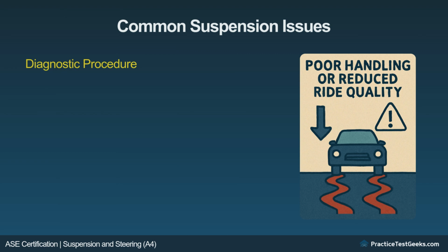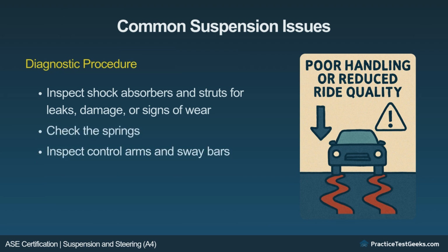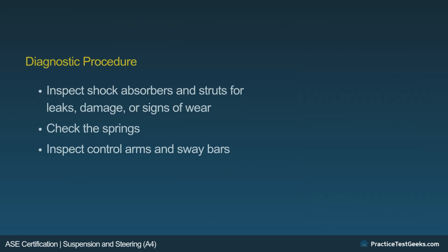Diagnostic procedure. Inspect shock absorbers and struts for leaks, damage, or signs of wear. Test for smooth movement by pushing on the corners of the vehicle and observing the rebound. Check the springs for sagging or deformation. Inspect control arms and sway bars for damage or looseness.